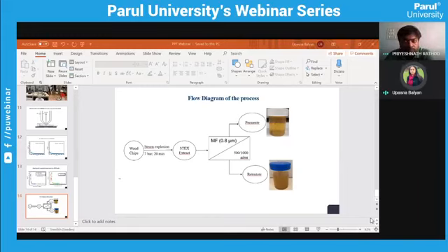Both processes can be used for purification. But steam explosion is just an extraction process, and when there are lots of suspended particles that are visible by the eye, you can use vacuum filtration followed by this, so that your system will be feasible to work upon with the membranes.